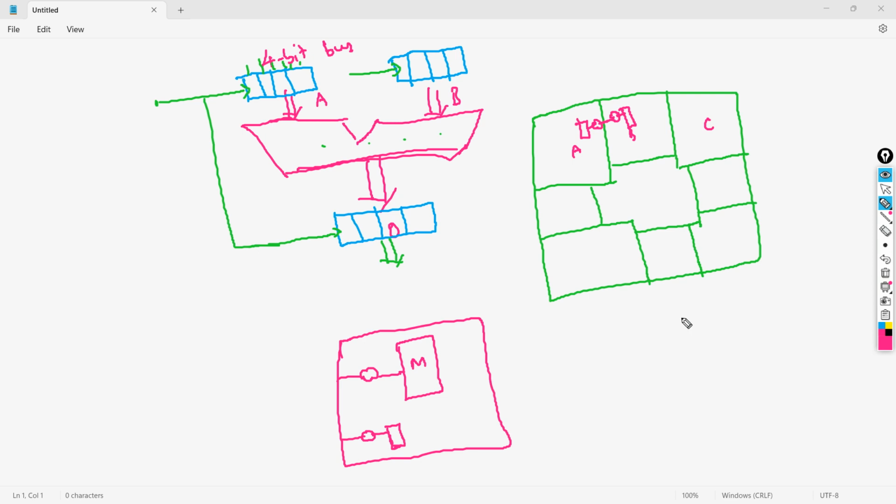Right now I'm just trying to cover basics so that you understand how these registers are used and why we need them. People may not realize the meaning of a register. I read it in college, in my engineering time, but where is it being used? So now when I explain this, okay, this is the reason why we have registers. We have to hold the data from changing very frequently, and you should allow changes only at the right time. So that means they are clocked, right? So that's a basic thing.